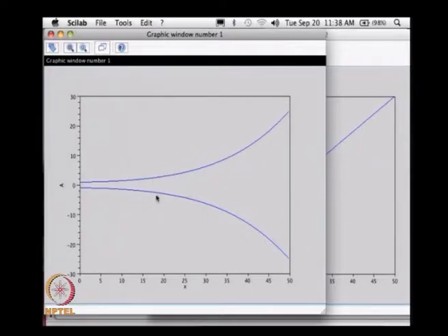As you increase the Mach number, the area has also increased, but the entire flow here is supersonic. For supersonic flow, as I increase the Mach number, the area is also increasing, which means that the flow speed is increasing. So this is supersonic here. For an increase in area, there is an increase in the velocity.